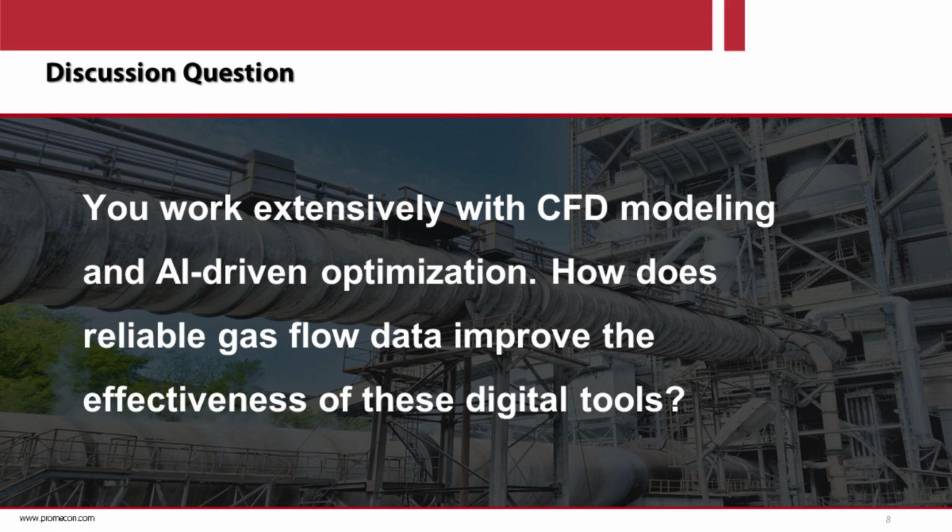So in case of an AI model, if you have data from measurements where the sensor is interrupted or the data delivery is interrupted or the sensor drifted, then you immediately degrade the performance of this model. So, in fact, the universal principle for modeling is also applicable here, which says rubbish in, rubbish out.